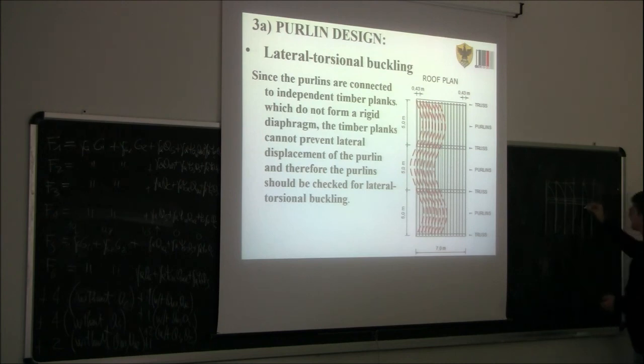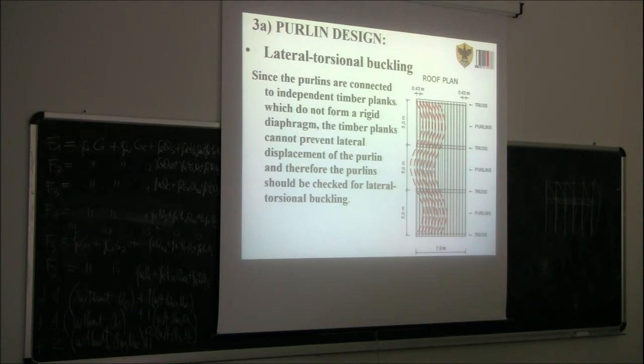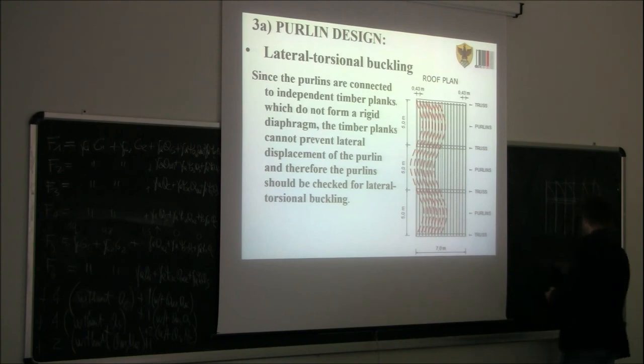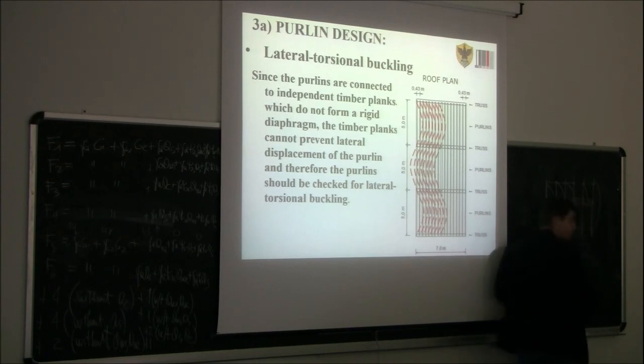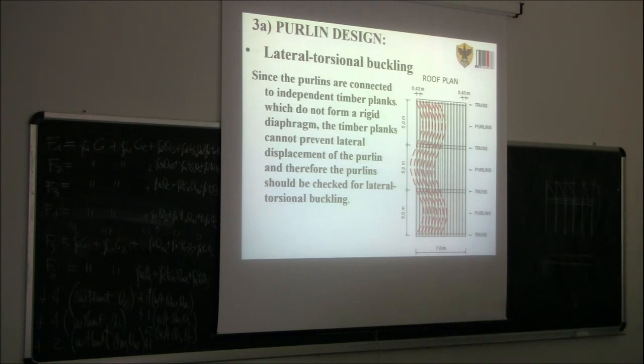Because what would happen is that all the purlins buckle all together, and those planks do nothing else than basically making all of them buckle together. So rather than buckling only one, you get all of them buckling together. This is the only effect of these boards. Because again, those are narrow boards, with maybe sometimes one nail, sometimes two nails. So they act as a truss, as an axial force, that's it, nothing more, if this was a floor, a plain floor.